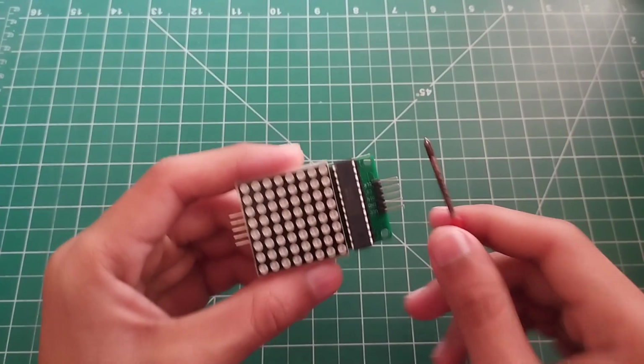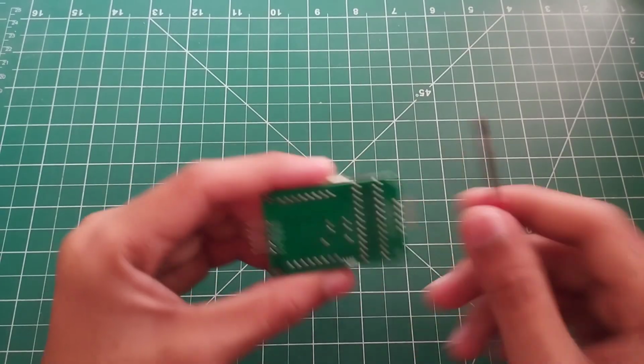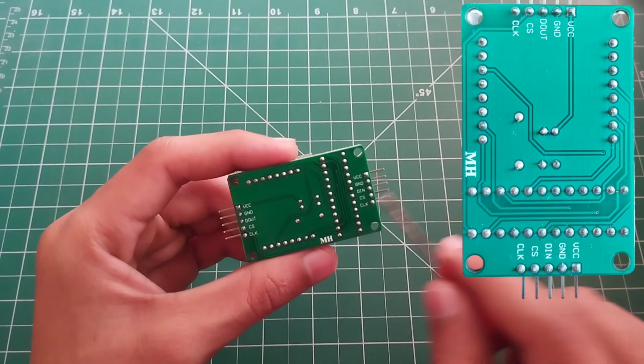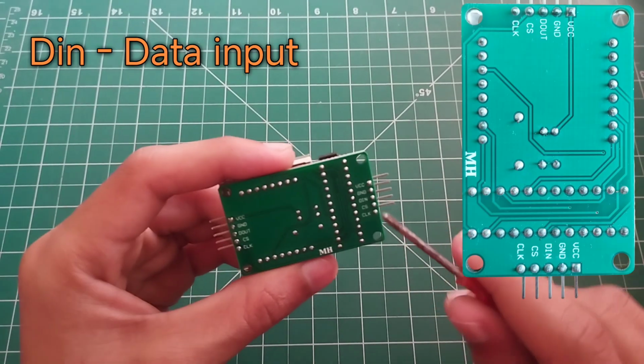Now before moving further, let me discuss the pinout of this 8x8 LED matrix display. If you see at the back of the display, there are a total of 5 pins here and 5 pins here. VCC and ground are obviously for the power. DIN stands for data in, which will be coming from the microcontroller like Arduino.